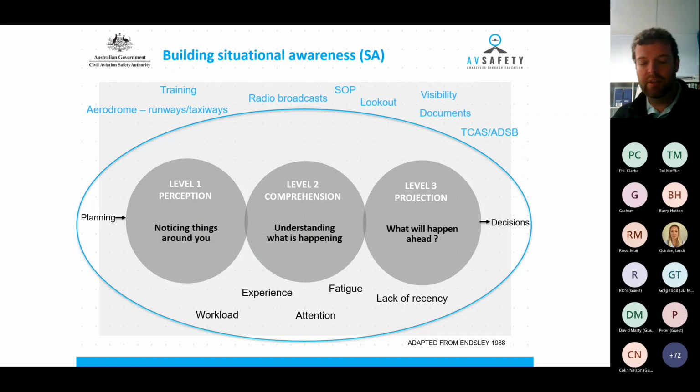Is it left side? So all these little things just keep building up, and eventually you start to run out of time, which builds up on you very, very quickly, and you're almost overhead the field with not much of an idea what's going on around you. And it can lead to an incident, that snowballing effect. So if you don't have that item one ticked off in terms of the planning phase, it just allows you to really fall behind the aircraft and miss more boxes.